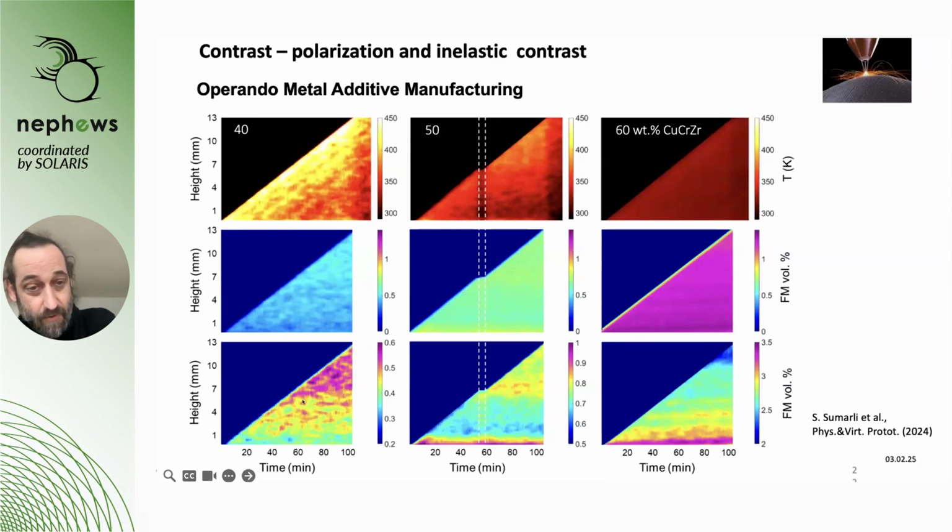And we see how we print more and more ferritic phase the longer we print, and the hotter the sample gets. And also what we find is, in principle, it is the cooling rate which defines how much ferritic phase we get. So when we print on a cold surface, we will get typically more ferrite than when we print on a hot sample. And that we see nicely here, where the print stopped for a while, and that means the sample cooled down. And in that instance, we suddenly built more ferrite phase into the sample as if we continuously continue printing.